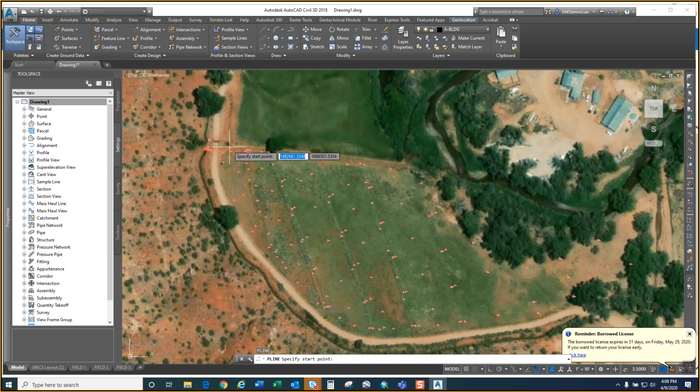Right now there's a ditch that goes all along here. We're going to do a pipeline that goes from the main irrigation ditch, which is all here. We're going to put a water control structure right here, a head gate, and then pipe this existing ditch and put one alfalfa valve on each of these fields, and we're leveling each of these fields.